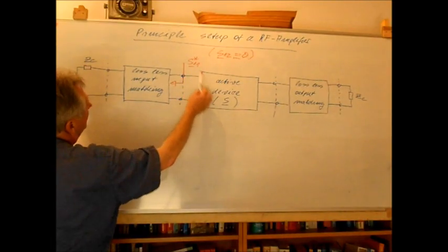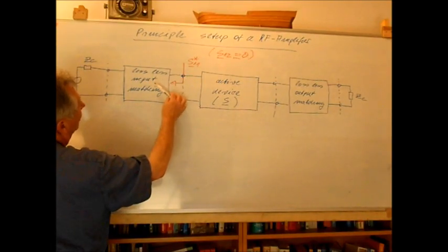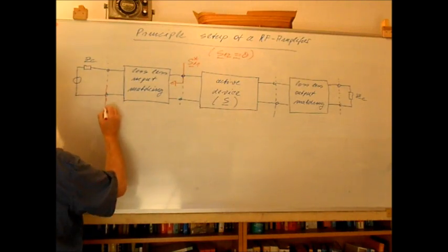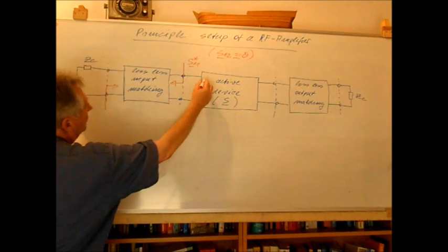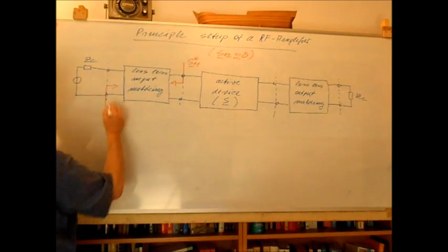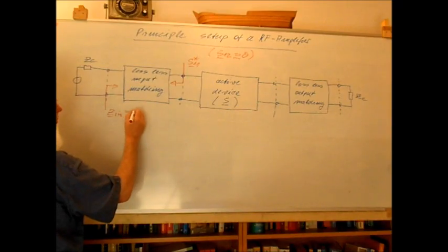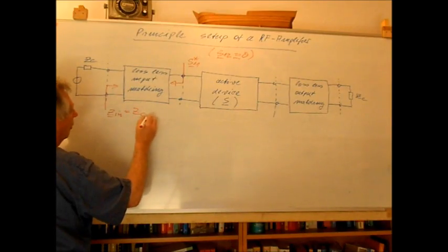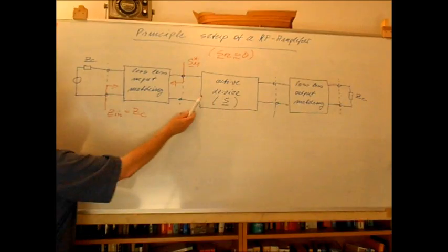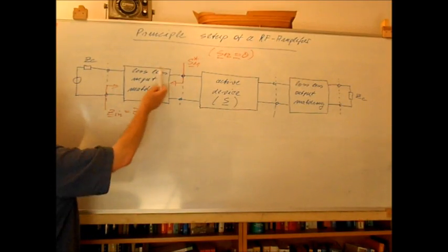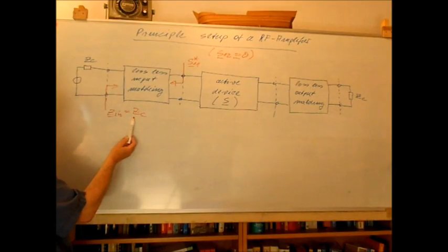So the transistor itself must see here Γ1, Γ2 conjugate complex, but this corresponds to the point that S11 of the transistor is transformed, so that the input impedance I see into this network must be equal to ZC. So S11 of our transistor must be transformed with the help of the lossless input network into the matching point ZC.